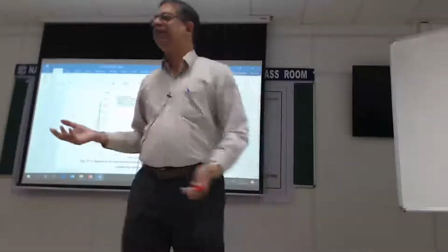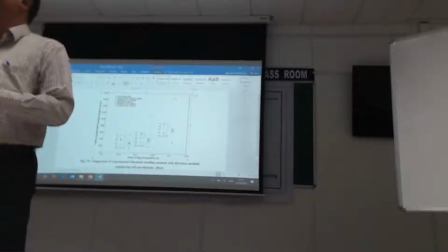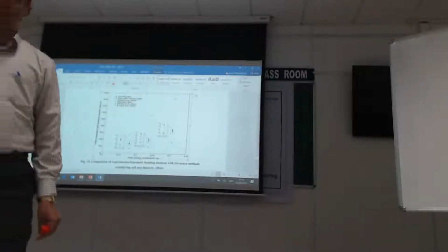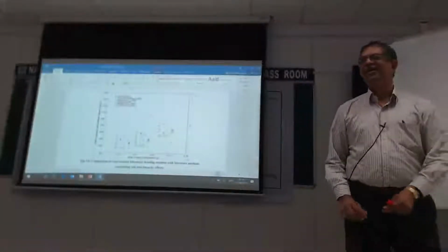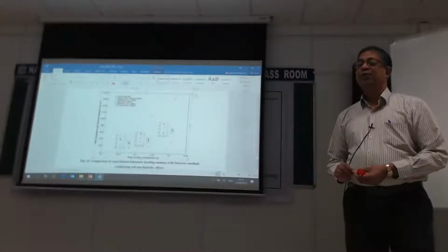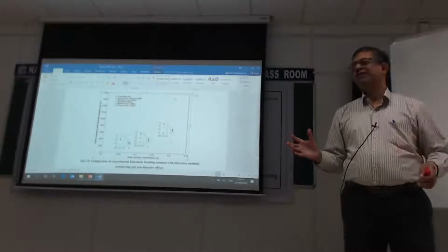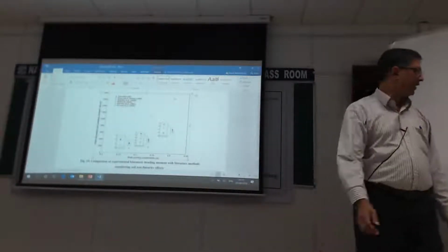So if you're doing finite element analysis, in theory, all this should happen within itself. Because in a FE, if you use the right constitutive model, it should be able to degrade your stiffness modulus proportional to the strain. Not all programs or platforms have the best constitutive models. There are much better ones than the ones that have been programmed in for you.